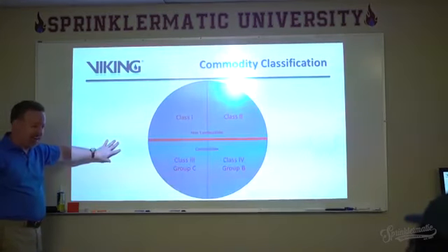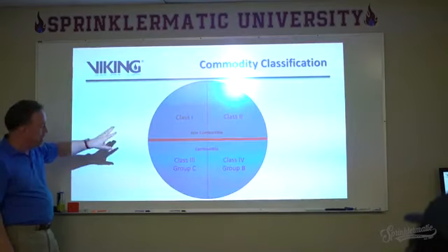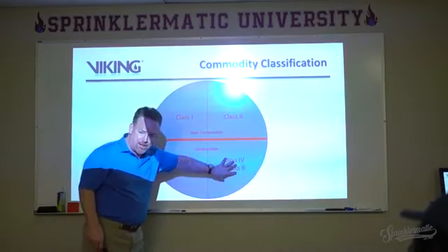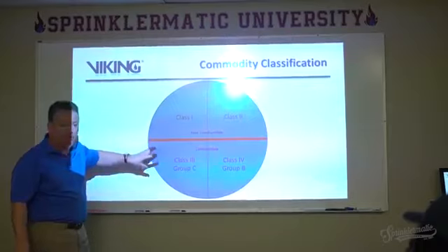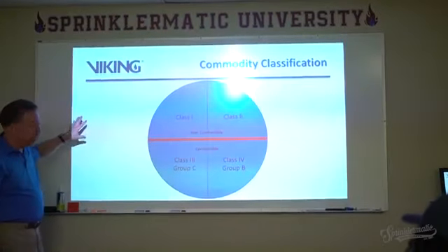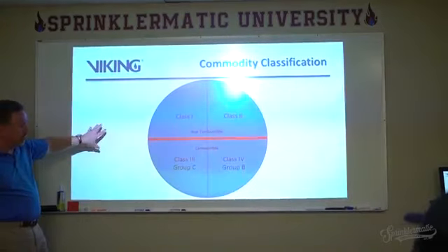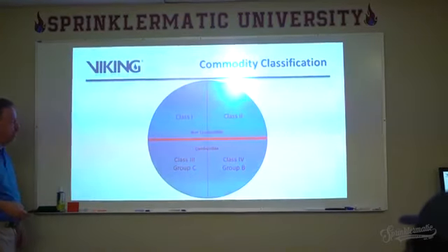The one thing that's not in here is the standalone Group A plastics. So remember that each one of these can have a certain amount of Group A plastics in it without being considered wholly Group A plastic to be protected. So these are the 4 basics, and then you've got the Group A plastic, the 5th one on the outside.